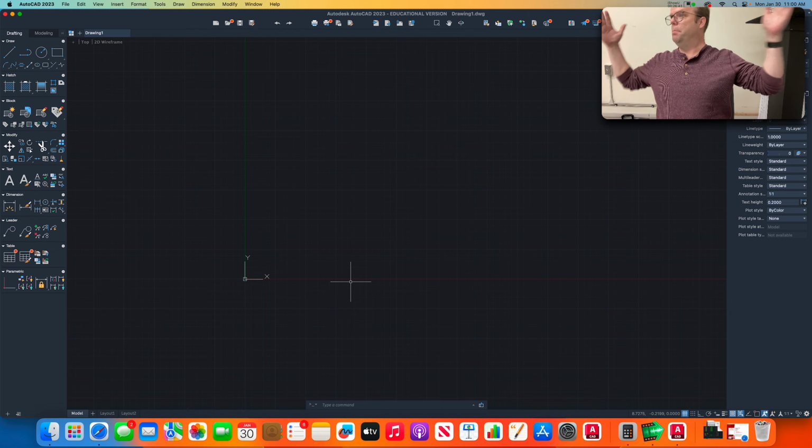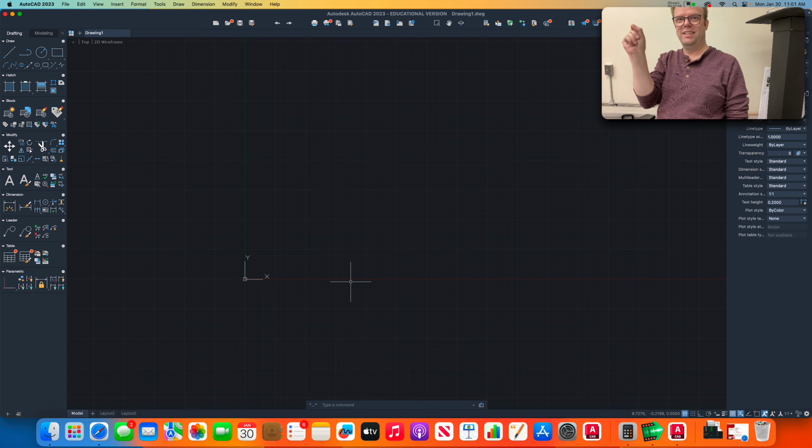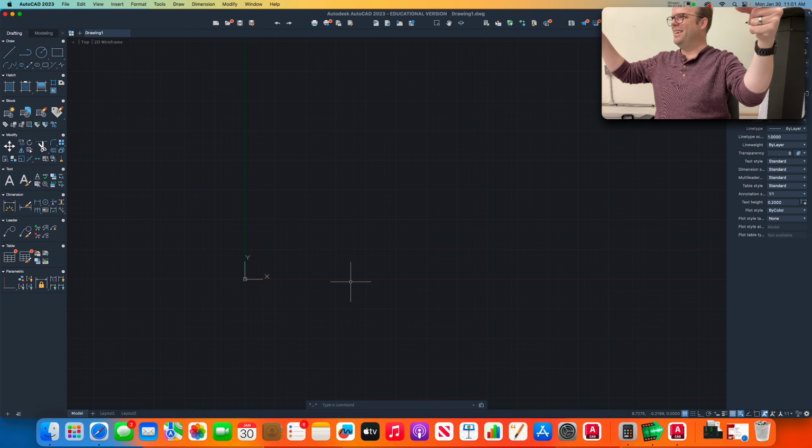In other words, you say, all right, I've got to make this drawing fit on this piece of paper, and therefore for every 1/4 inch of space that I draw, that will represent 1 foot in real life. 1/4 inch equals a foot. Or for every 1/2 inch I draw, that represents a foot in real life. That's called scaling. And you can actually buy rulers that do this for you, already labeled in actual feet, but everything on that ruler that says 1 foot, 2 foot, 10 foot, 20 foot is actually representing 1/2 inches, okay?